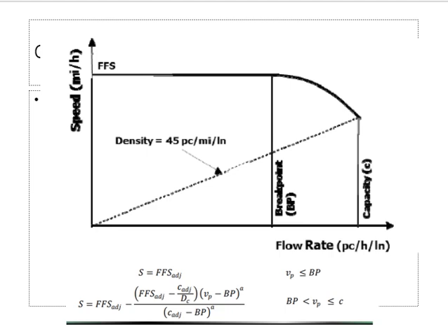Got it? Clear? Now if you have to plot the first part of the graph, the line, you only need one value: what is the speed? You will draw a line, and you need the end point, which we call the breakpoint. For the breakpoint we have an equation. And this speed is FFS, the free flow speed.